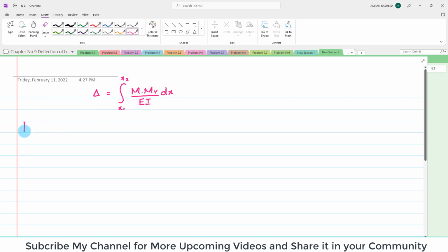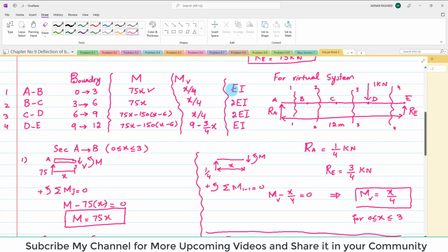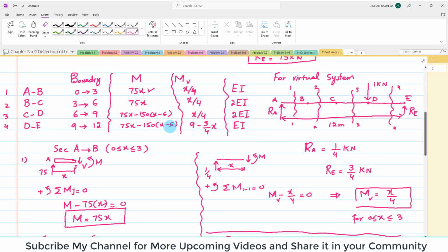So deflection for AB, we can write delta is equal to 1 over EI. Here you can see EI is the same, so we will take it out. Integral from A to B, the limit was 0 to 3. M for this portion is 75x, and MV is x by 4.